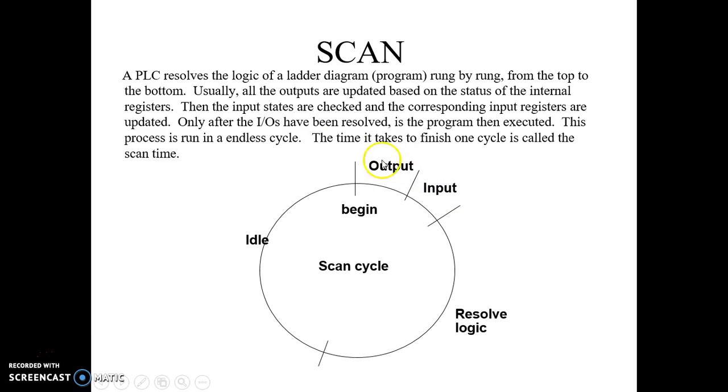Now how does a PLC work? A PLC scans output images as well as input images, and it also scans the program which is preloaded by the user as per their need. At the beginning it delivers whatever output image was created by the PLC as per the previous status of the program. It delivers the signals to the field and also creates an output image which is stored in memory as the output image. After that it scans all the inputs from the field and creates an input image, which is also stored in the memory as the process image for input.